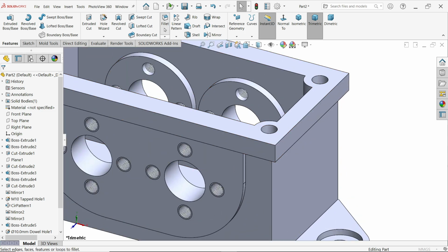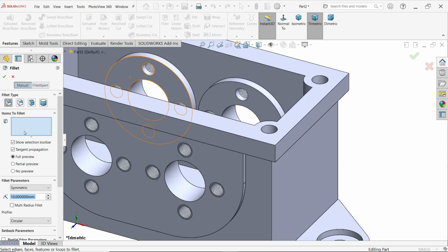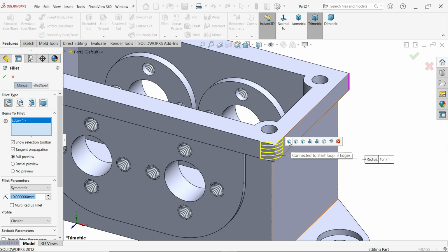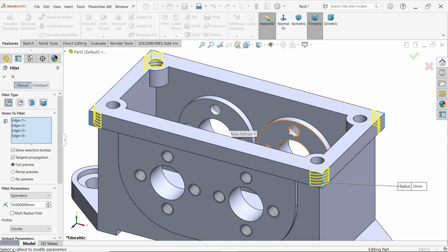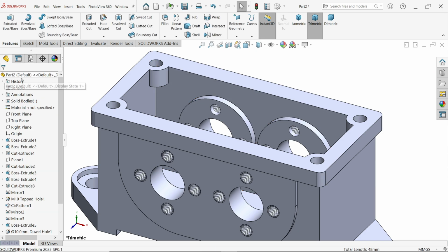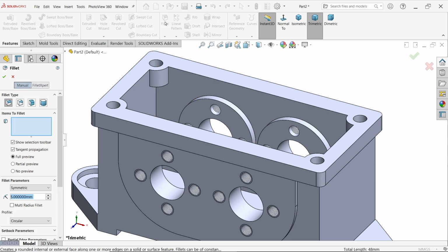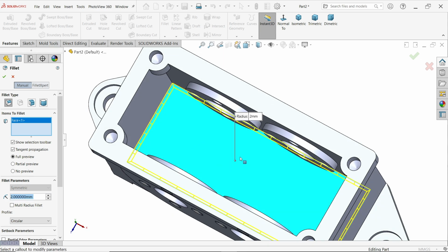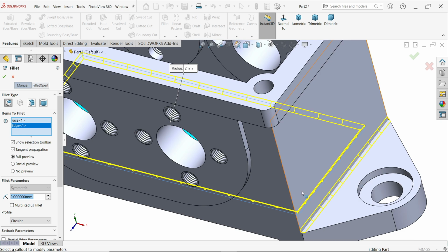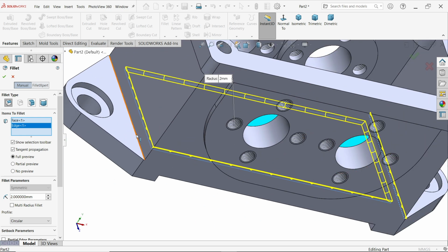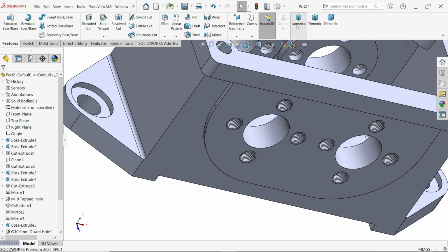Now activate fillet, constant type. Now from here I am going to select this edge, and it will show you this option. If you choose this first one, it will select these 4 corners. You don't need to select one by one. Parameters symmetric 5 millimeter. Now again I am going to select fillet. This time put 2 millimeter constant type, and here I am going to select inside face. Parallelly, let me choose this outer edge and this outer edge. Okay. See.